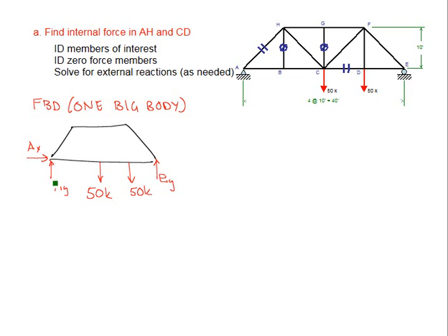In order to make a complete free body diagram, we need our coordinate axis system, X and Y, and we need to make sure that we denote all of our dimensions. We're now ready to make use of our equations of equilibrium, but before we can, we must classify this force system. This force system is a non-concurrent force system, as the lines of action of all of the forces do not intersect at a single point.